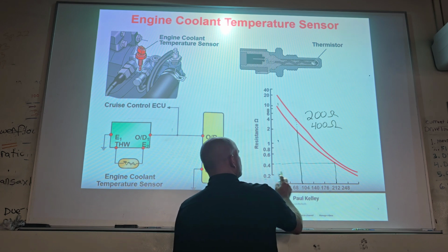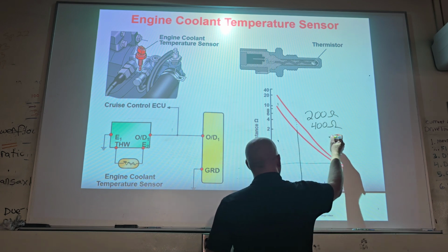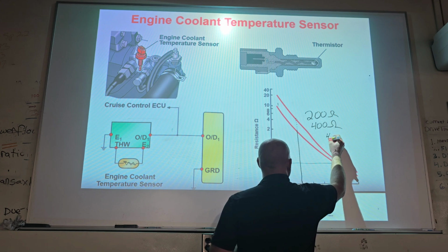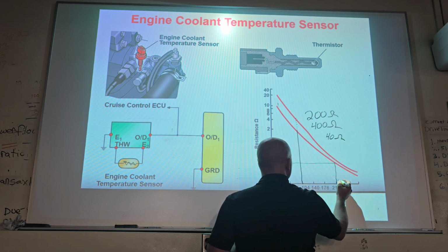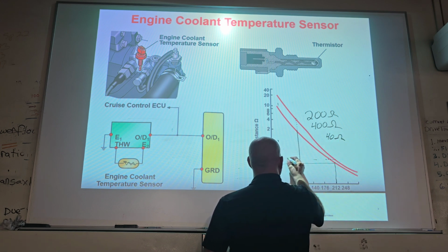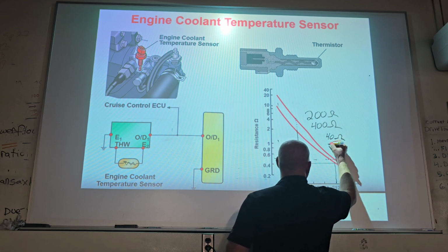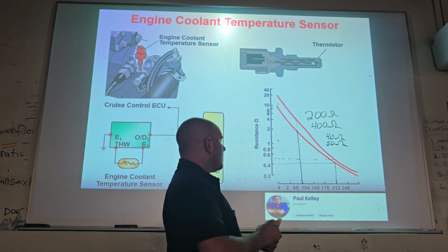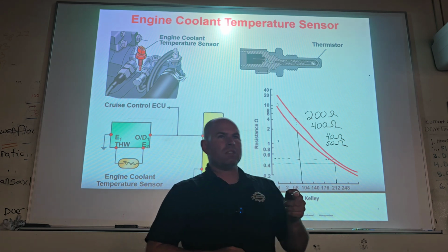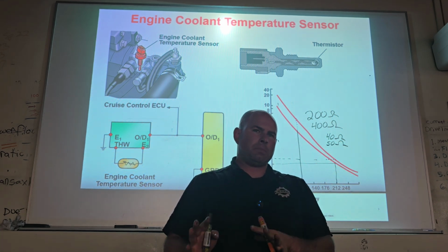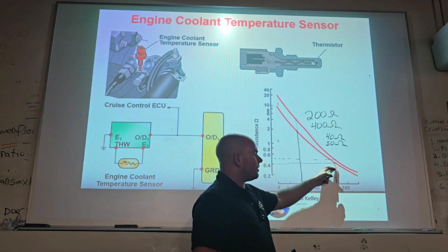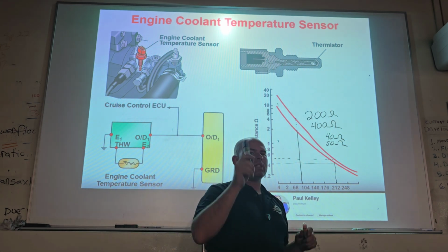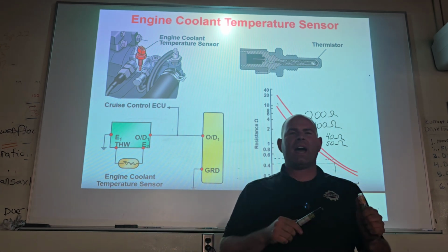Interesting. So 212 is going to be about 0.400, so that's 40 ohms, to about maybe 50 ohms. You understand? So when you measure the resistance, it's not just is it in spec, it's does it correlate with the temperature. So now here I'm going to give you a good old flat rate hack.